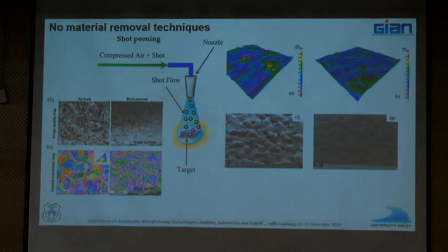It does refine the grains quite a bit. It's almost similar to this. You see a big difference in the extent of refinement. And again, everything is almost a science. You can call it bead blasting, but there are many variables in this. At what velocity do you blast? What compressed air pressure do you use? What is the shot size?